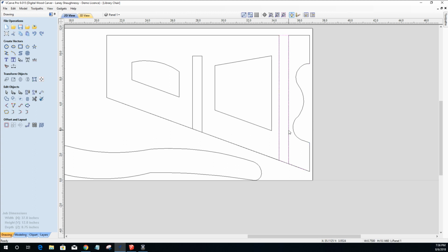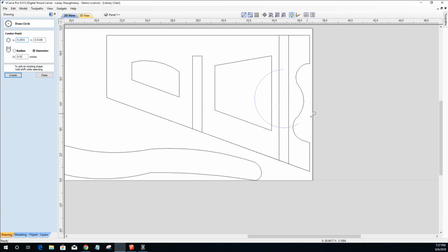Now that vector here for the 1/4 inch deep, 3/4 inch wide spline, that's kind of important. I don't think I would make this chair without it, because the area in here is short grain, meaning there's not a whole lot there.